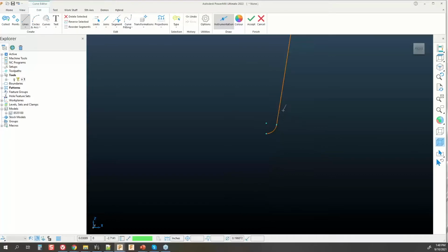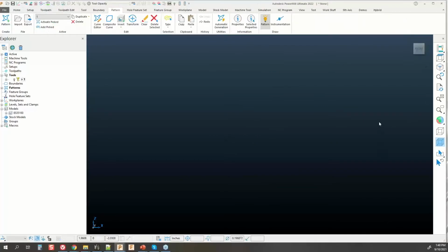And we can actually get that distance off the angle. You can snap a line to kind of gauge what that angle is, and then of course measure that line to get that data. And that's how I can get where maybe I want to contact on that type of tool, what that successful angle is. I'm just going to measure the angle of the line that I created tangency to the cut itself. I'm going to cancel out of that, jump back into PowerMill.